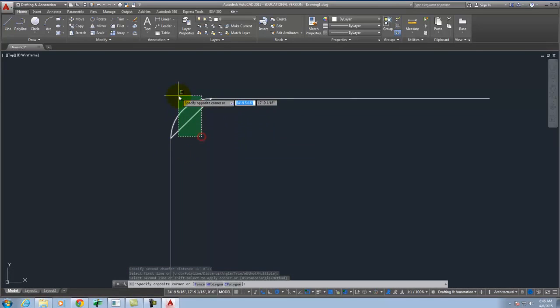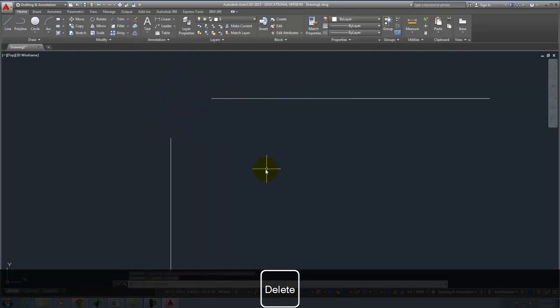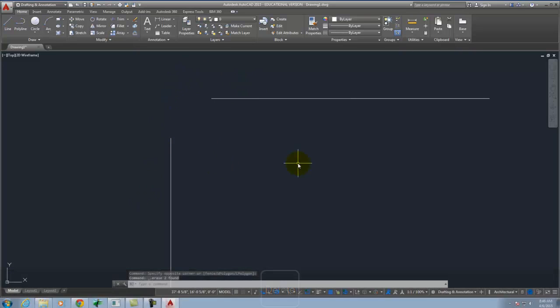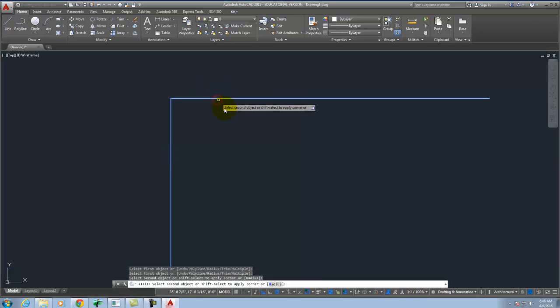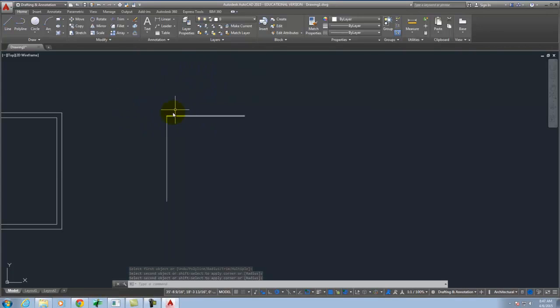The other thing that's very useful, and this may be for those of you that are more experienced in AutoCAD, one of the fastest ways to get two lines to connect together is to do a fillet with a radius of 0. When you have two lines in space, you can get those to come together into a nice corner very quickly. I use that frequently when I'm working. So you can just set the radius to be 0, and you get a 90-degree corner.